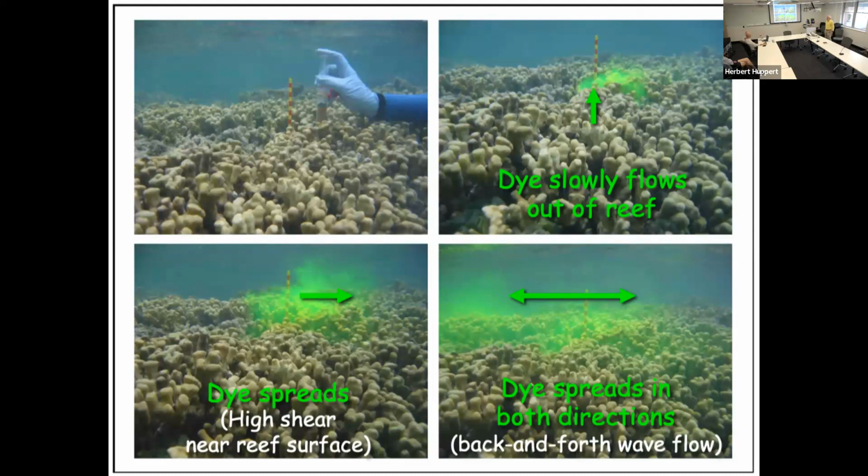Can I ask a question quickly? Please. So the Darcy flow, the approximation for that would be that it's laminar in there, low Reynolds numbers. Is that right? It's a low Reynolds number laminar flow, and I'm assuming the most simple porosity and using Darcy's law.